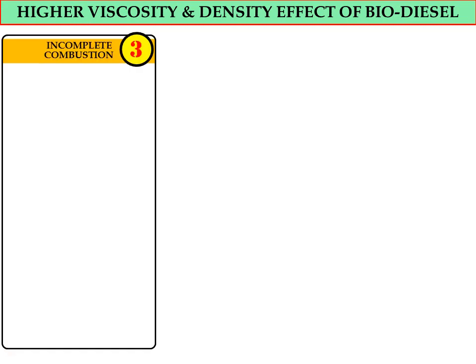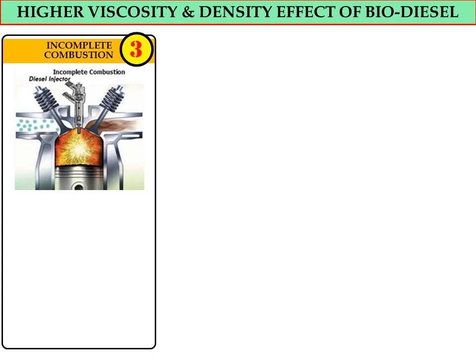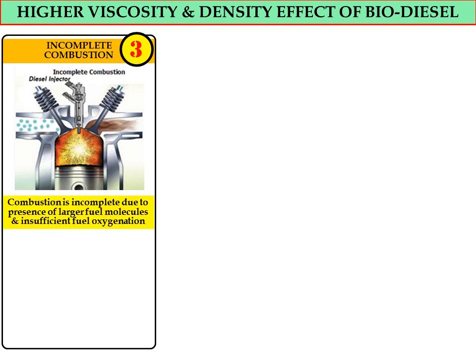Effect number 3 is the incomplete combustion process. The figure shows the effect of incomplete combustion, where we have the formation of deposit, which refers to the black particles inside the combustion chamber. Combustion is incomplete due to the presence of larger fuel molecules and insufficient fuel oxygenation.